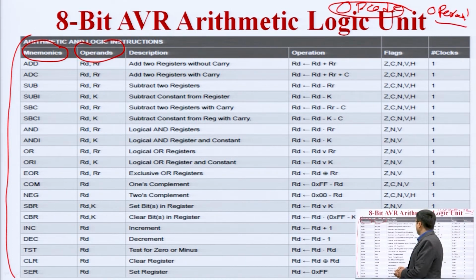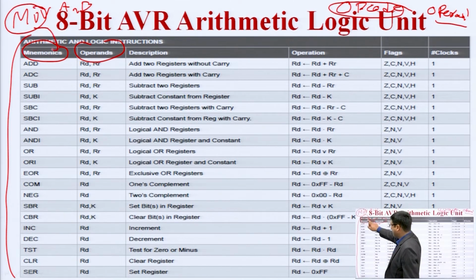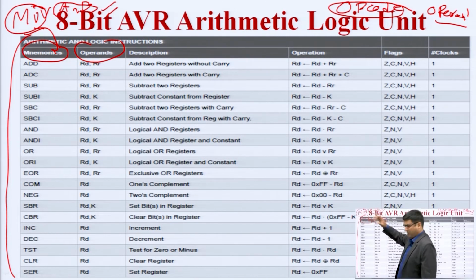Okay, so let us take the example MOV A, B. MOV is an opcode, an operational code. We can say it is a mnemonic. What the microprocessor has to do is told by the opcode. Move. So basically, we are looking into this instruction. Move means that we are moving something. We are loading the data from one register to another register.